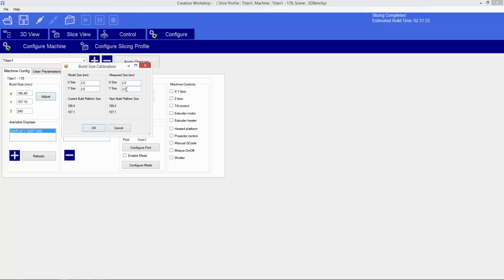taking shrink into account. The problem is that shrinkage affects negative space and positive space differently, right? So a sphere is all positive space, whereas a donut has a hole in the middle. There's some negative space. And when you shrink, if I take shrink into account based on the measured outside dimensions, holes will become way, way, way too small.